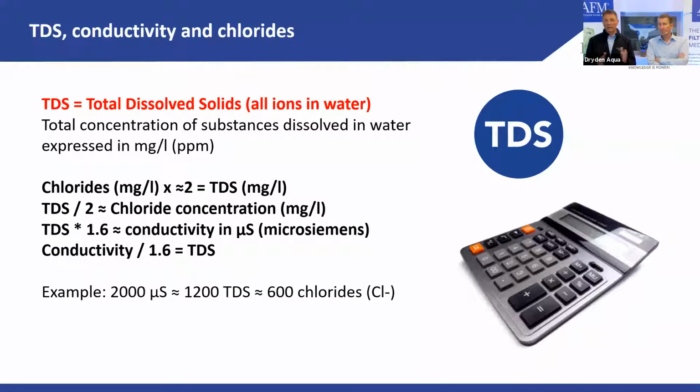If you have water completely demineralized, there are no ions in the water, TDS is 0, current will not flow through the water. Only if there are some ions in the water can it really flow through. This measurement, how easy these electrons can flow through the water, is called conductivity. You can easily measure it with a very cheap $10 or $20 conductivity meter, which measures this in microsiemens.